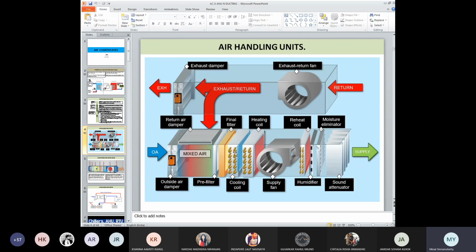Okay, then you have your cooling. So here what they've shown is they are allowing the outside air here. I will not opt for this because this has a lot of impurities. But as of now, nothing has passed through the filter media, so it's okay. If this air is coming in, it is still getting filtered here. So this is the outside air damper, which allows the air to come in. Then the air here and this air are getting mixed up.